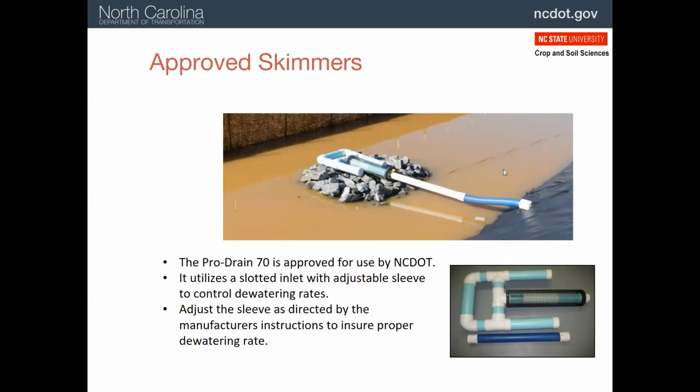The standing pool that you end up with after that is actually a good system for allowing the dirtiest water after each event to stay in the basin and let it settle out some. And also it provides a break or a way of slowing the water that comes in on the first flush that comes into the basin. So there are several good reasons to keep a pool of water in the basin, as you can see here.